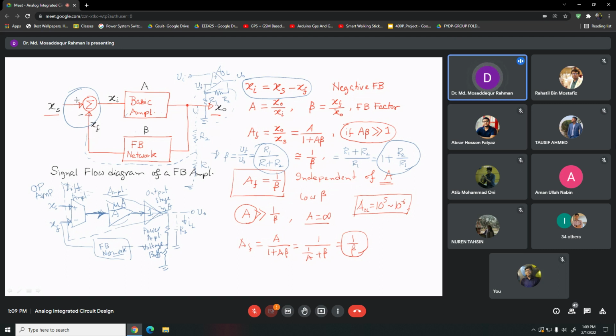There are high power op-amps as well that can go to hundreds of milliampere or maybe ampere. If you want ampere range current, then you add another power transistor at the output, external to the op-amp. Most op-amps are designed to handle at least current in the milliampere range. The op-amp that we use in the lab can handle about 20 milliampere maximum.